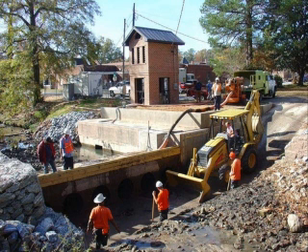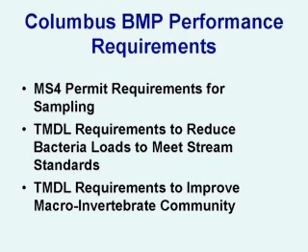When the event is over, the next day, these filters are not backwashed during the event, but they're backwashed after the event. The city comes in, hooks up this blower to each of those. There's 3 filter cells there, and the operator just hooks it up and turns on the blower, and in 30 minutes the filter's cleaned. And they remove trash from the upstream side of the flow control, which collects a lot of material.